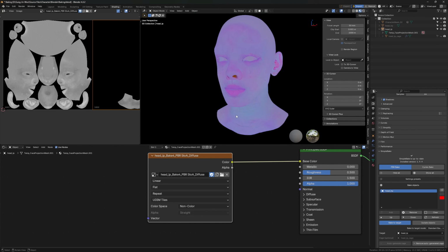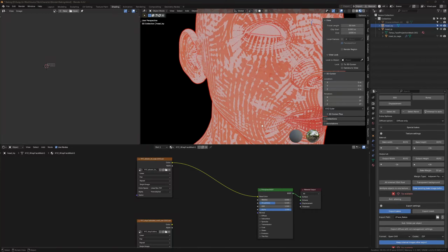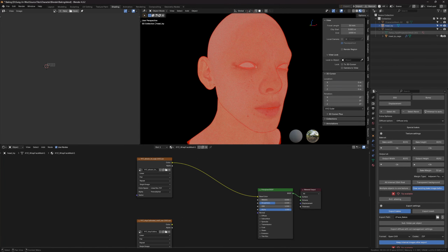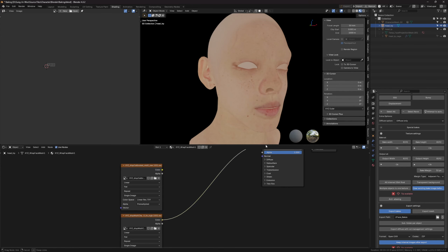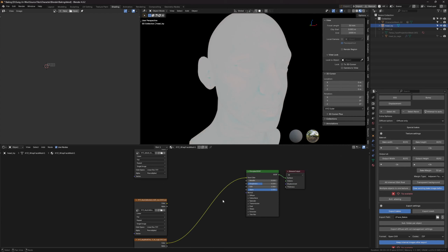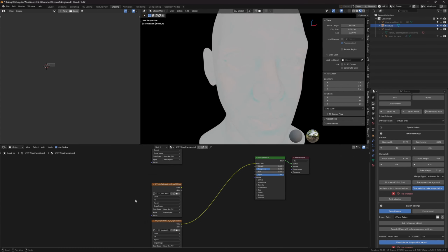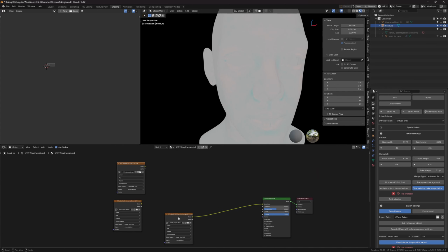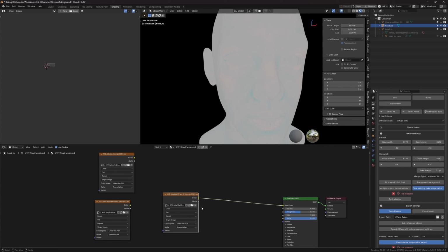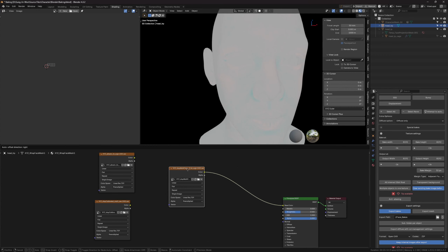So this is how you bake high poly to low poly in Simplebake in Blender, and how you transfer the details from TextureXYZ, VFace, or any of the TextureXYZ base meshes to low poly or the meshes which you created. I just want to quickly point out something. When we are baking maps like the utility map or displacement multi-channel, what I was baking is the map itself with all the three channels, but there is a way to separate these channels and bake them as RGB channels. This cuts the process of importing it to Photoshop and exporting it in separate channels.